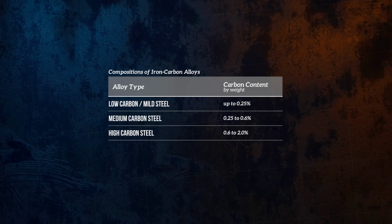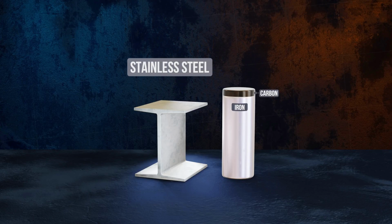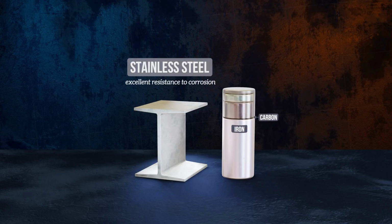Between 2% and 4% carbon, we obtain cast iron. It has good fluidity, and the additional carbon lowers the melting point of the alloy, making it good for casting, although it tends to be brittle. We can add additional elements to the iron-carbon mix to obtain specific properties. Stainless steel, for example, incorporates chromium to provide resistance to corrosion, the most common being Type 304 stainless steel that contains 18% chromium and 8% nickel.